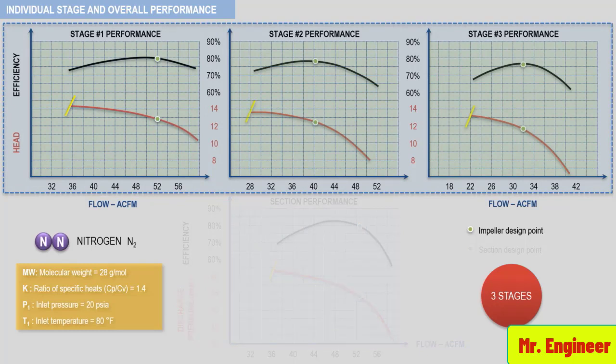The only opportunity that you have to review these curves is prior to an order or during a design audit. So, I strongly advise you to review this information during the bid phase of a contract to determine if all individual impeller operating points, when operating at the rated point, are as close as possible to the individual impeller best efficiency points.